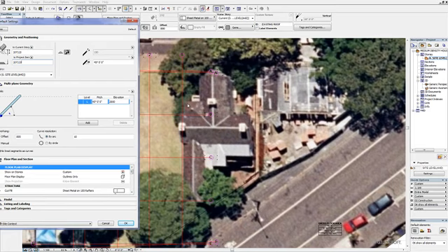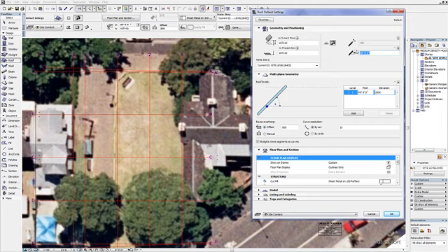So we're going to leave the RL to project 0 as it is. We're going to put the slope of the planes of the roof at a 45-degree angle. Okay, and I'll explain why I've assumed it to be a 45-degree angle when we look at the side elevation photo. What you'll notice from the side elevation photo is that it very much looks like a 45-degree roof,